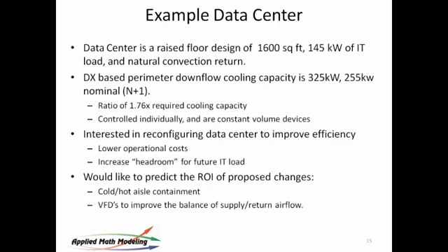So here, in this case, the customer, of course, is interested in how can I reduce my total energy consumption? How much is it going to cost me to do that? And the approach that is optimal for our purposes is VFDs, because what VFDs do is they allow you to vary the air supply amount, the quantity, the volume, to match the needs of the equipment in the room.